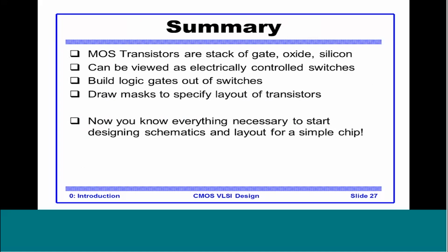So what we saw in this chapter was the very basic nature of the MOS circuit, how the MOS is made up of gate, oxide and silicon. The functionality we are most interested in is whenever the MOS acts as a switch, since all the basic logic gates can be made out of a combination of switches. We saw the inverter layout, and this gave us an idea into how the circuit is laid out, obviously at a very basic level.